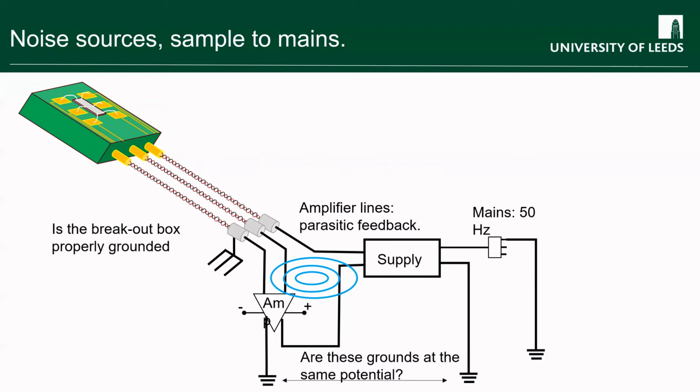And again, you see here we've got 3 lines joining between our sample and the equipment. So if all of those were shielded cables and the grounds were all connected together at the sample end, then you really mustn't have them connected at the electronics end, your measurement electronics end, because otherwise you've just created a couple of nice ground loops, which you don't want, because a ground loop like that will have an inductive pickup and will therefore generate voltages in what should be an earthed signal. And that will then affect your screening properties. So there's lots of scope, if you're not careful about drawing out a nice circuit diagram and thinking about how everything goes together, that you can introduce additional noise sources without really meaning to.